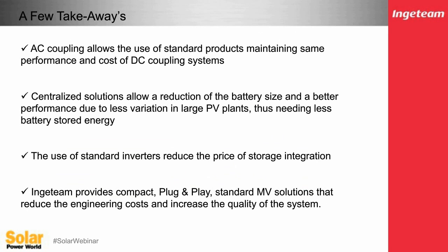A few takeaways from the webinar. I emphasize that the AC coupling does allow standardized inverters, and therefore you get to take advantage of the DC inverters and the battery inverters to optimize each system. The centralized solution allows a reduced battery size in a ramp rate control application, therefore a more cost-effective manner to design the entire plant compared to a distributed system.